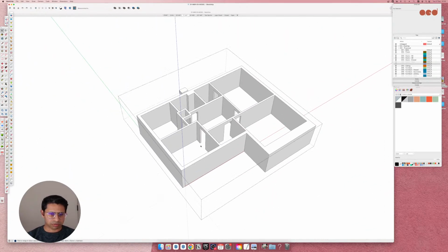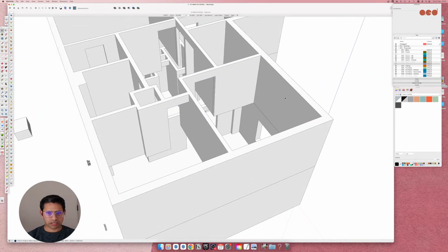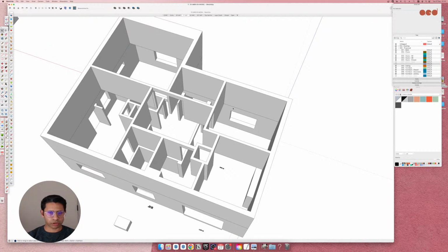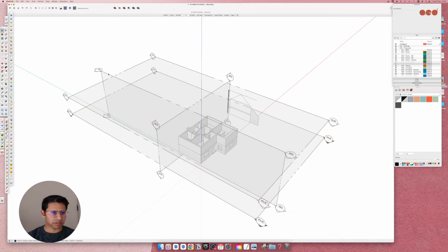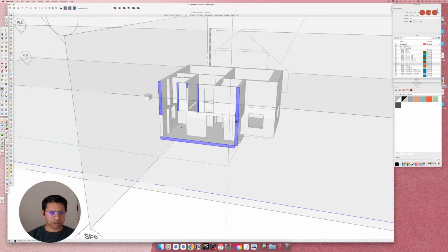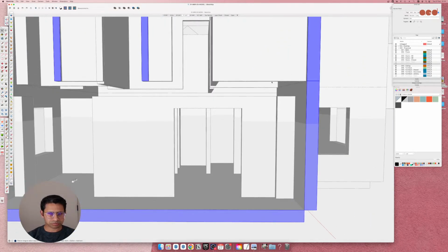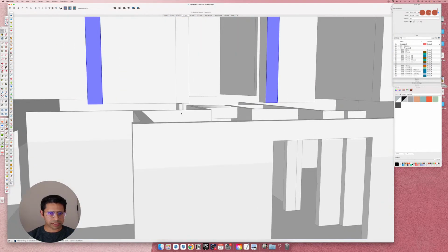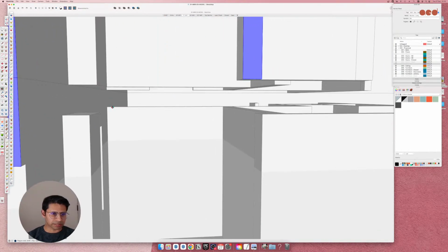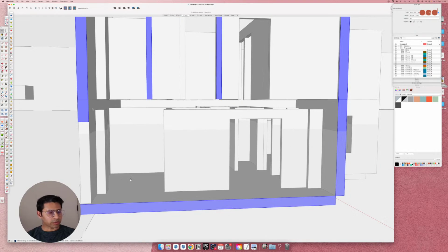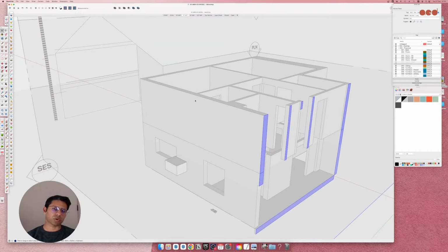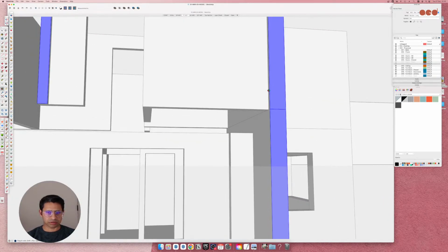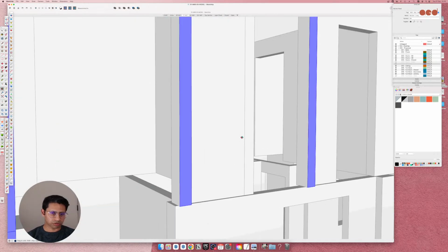I've just modeled the walls. Now there's one problem that we will see once we start modeling the floor, because the way it works is if I switch on my section planes and reverse this section, you could see that the walls here, now it's not a problem, but the reason why we extended the external wall beyond the underside of the ceiling level is because on the outside we want a continuous wall, whereas on the inside the internal walls don't continue through to the next floor.